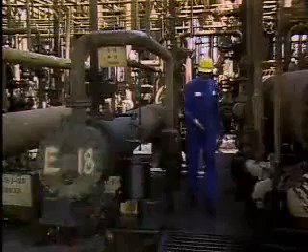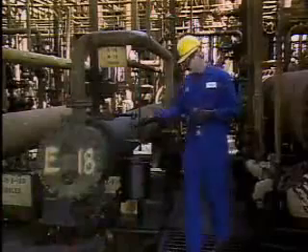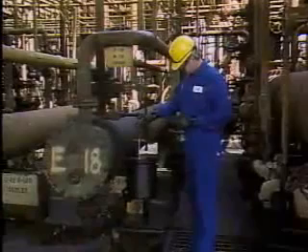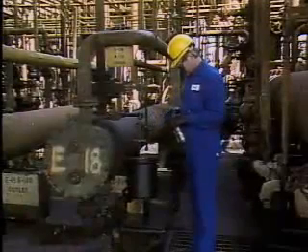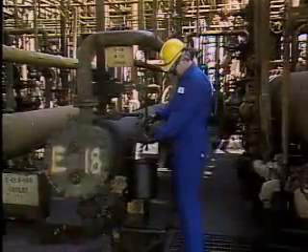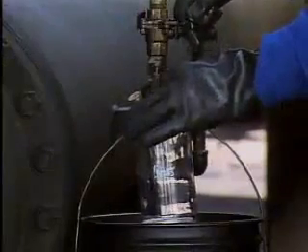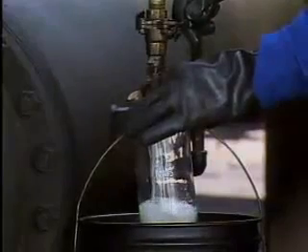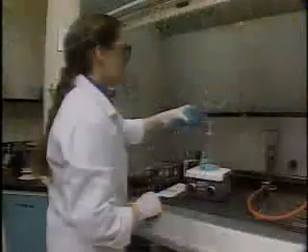One way to check for tube leaks is to take and analyze a sample of the lower pressure fluid. When a leak occurs, the high pressure fluid leaks into the low pressure fluid. In some cases, you may be able to tell there's a leak by just looking at the sample. In other cases, a lab test may be required. To prevent leaks in some applications, the process fluids pass through filters or strainers to remove impurities that can erode the tube metal. Also, chemicals may be added to the fluids to control corrosion.